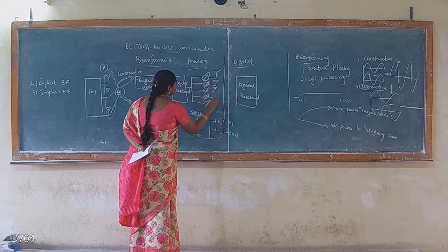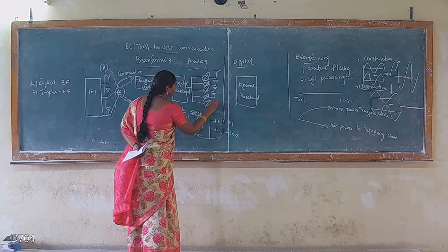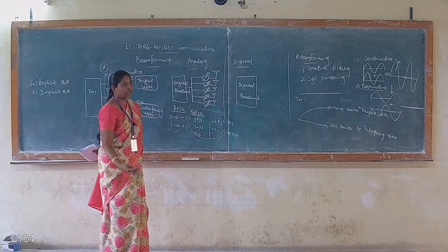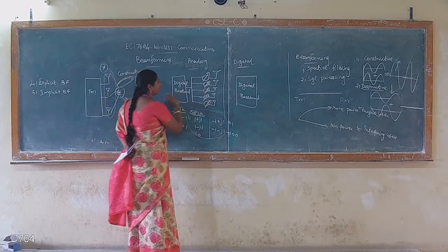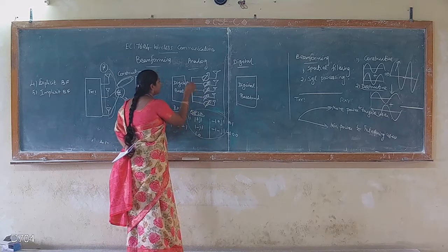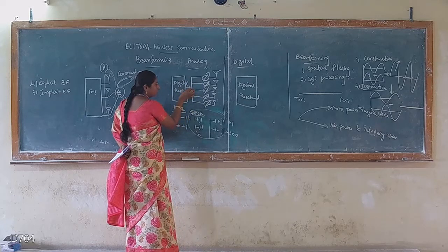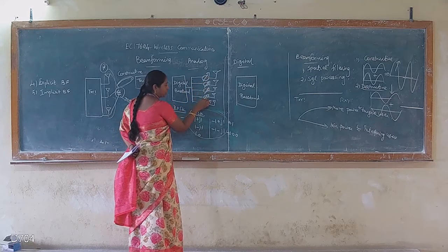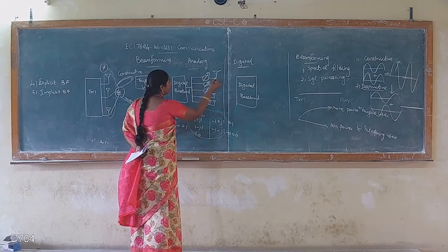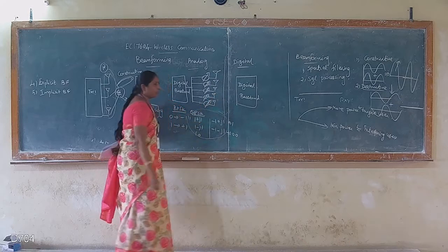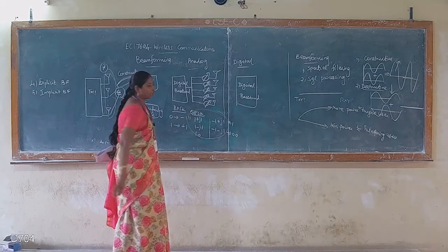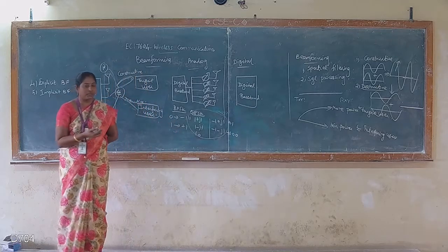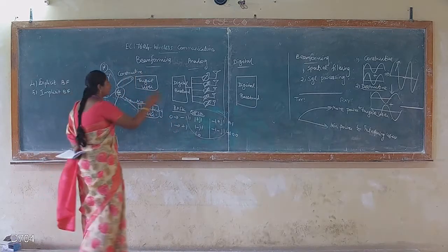We have an array of antenna elements. More than one antenna element is called an antenna array. Across all the antenna elements, we transmit only one signal. That signal undergoes different phase shifts, and the differently phase-shifted signal is transmitted over every antenna. This is the principle of analog beamforming. Whatever the amplitude variation and phase variation, everything is done at the analog level.